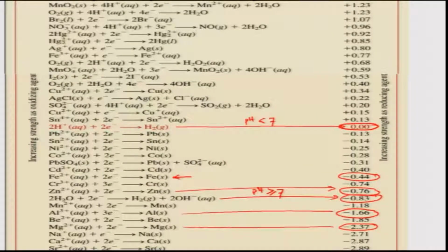Aluminum is a problem, though it can be used if we maintain the active nature of it. Aluminum has an inherent tendency to get passivated. When it passivates, it forms aluminum oxide on the surface, so then it will no longer remain an active component. So, aluminum has a problem. We will discuss that later, but for the time being you see that